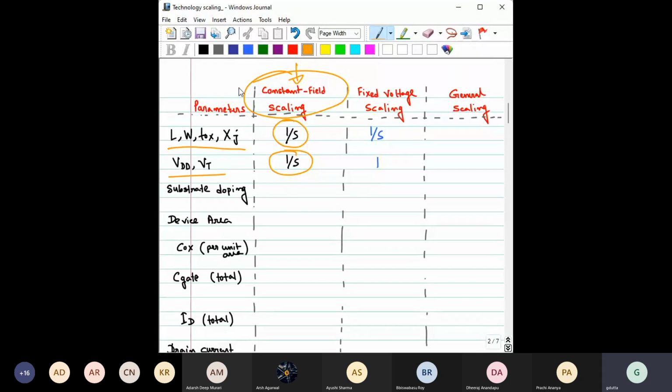Fine. So, why do we need that constant field scaling? Because if we keep this VDD constant and only reduce the gate length and the source and drain distance and all these things, then what will happen? There is a property of each material called the breakdown electric field. Once that breakdown electric field is reached, the device will be permanently damaged. So we cannot do that. Let's first focus primarily on constant electric field scaling only, then we'll see other variations.